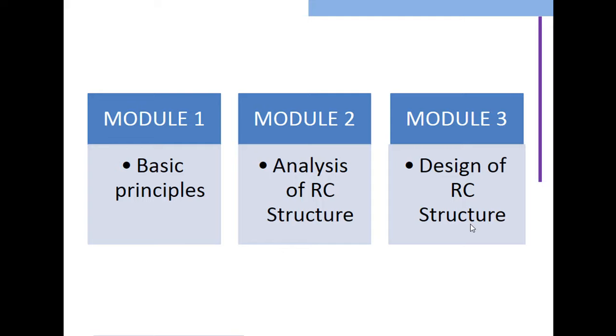Look, each and every time you are going to design any kind of structure, you need to analyze it. Without analysis, without a proper description of the shear forces and bending moment, you cannot design any kind of structure. If you are going to analyze any sort of portal frame, any beam, any foundation, whatever it is, you need to assign proper load. If you don't know the loading condition, you're not in a position to do the proper analysis. So it is very important to go with the basic principle, then analysis, and then the design of the RC structure.